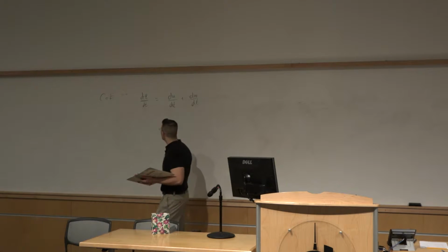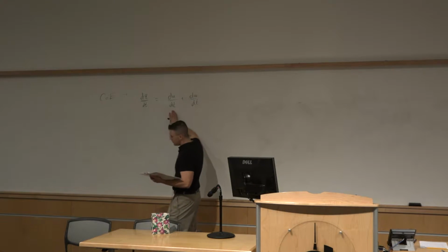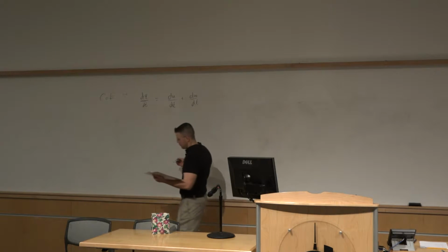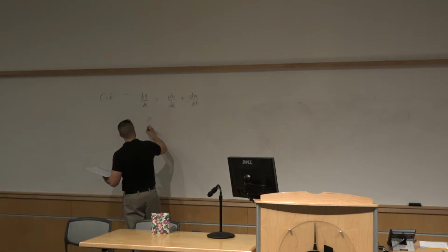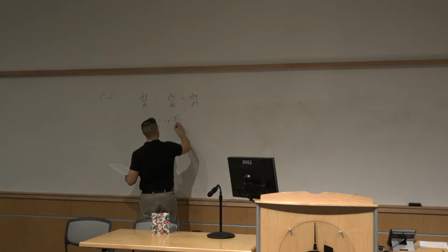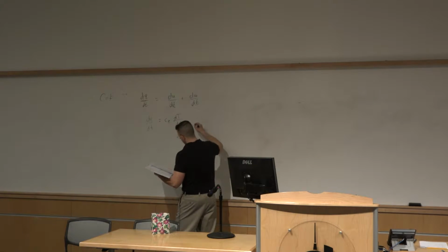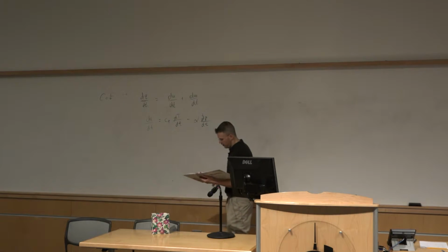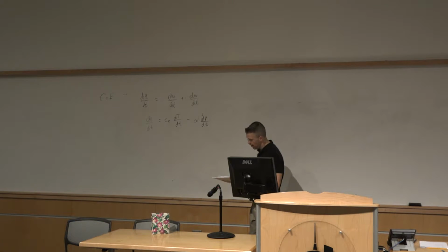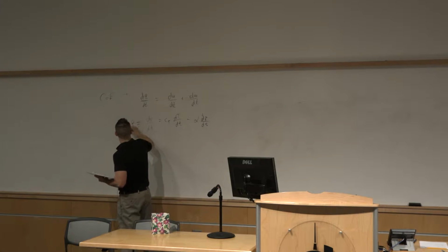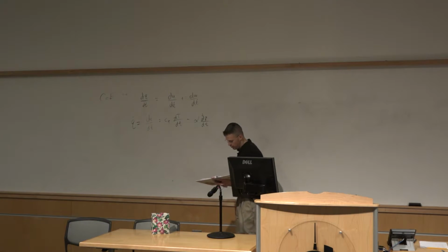And what you'll be seeing in midterm exam number 2, which you'll be getting today as a take-home exam, is that you're going to write this statement of the first law of thermodynamics in the enthalpy form, which I'm going to write out over here. You'll be performing the derivation for this in the examination. dq/dt is equal to Cp, specific heat at constant pressure, times the change in temperature with respect to time, and this is in Lagrangian form, minus alpha dp/dt. You'll show how that goes from this later on. And we're going to call this quantity, the change in the energy exchange with respect to time, Q dot. That's the change in energy with respect to time.